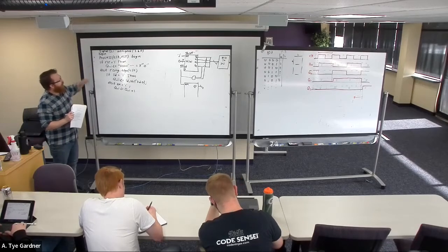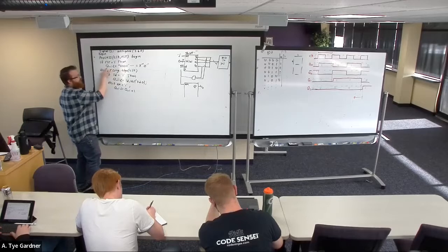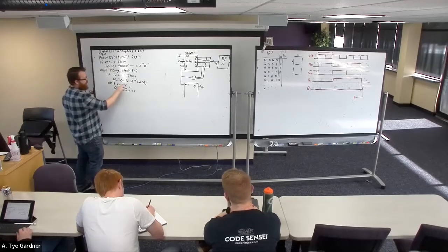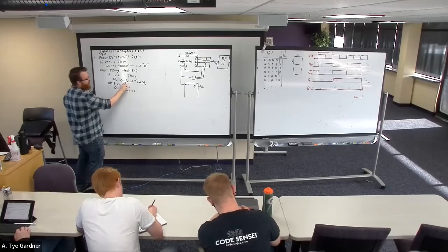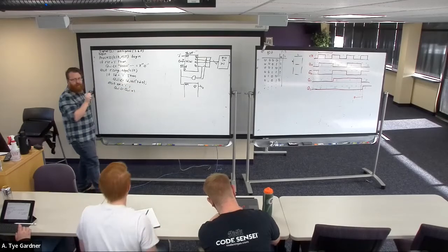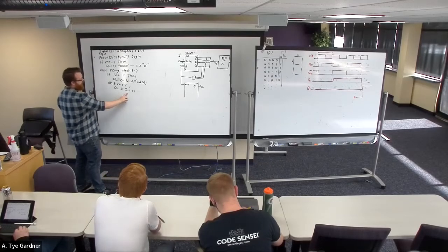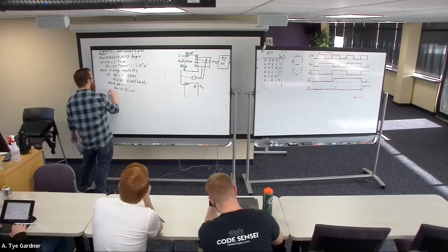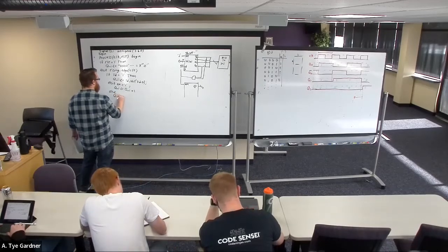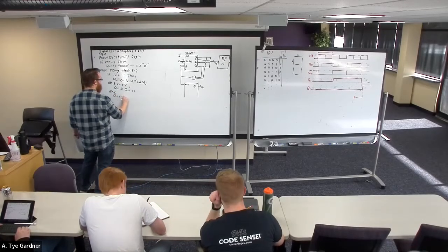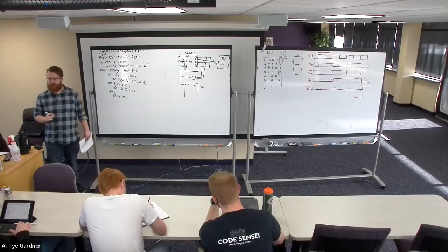So now this is still allowed. I can still put 4 zeros into my unsigned. I can still take, well, this is not quite right. This one needs a data conversion type, which I'll show you how to do in just a second. And then this is allowed. And then we say else QI stays QI, right?